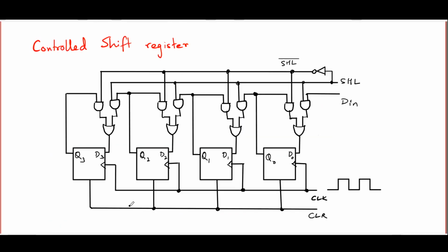The final circuit that we are going to talk about today is a controlled shift register. This is very much like the controlled buffer register. In fact, it's nearly identical to that. So I will not bother explaining its action all over again. All I will point out is that instead of the right end AND gate being fed x0, x1, x2, x3 as before, it is actually being fed from the output of the previous one.